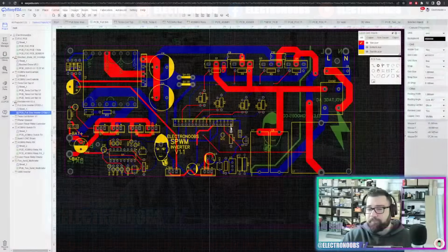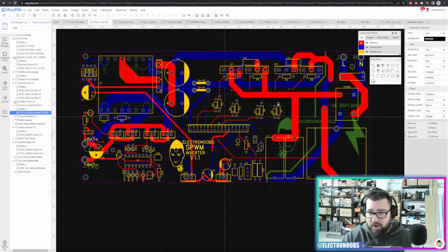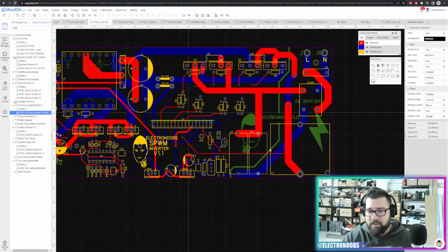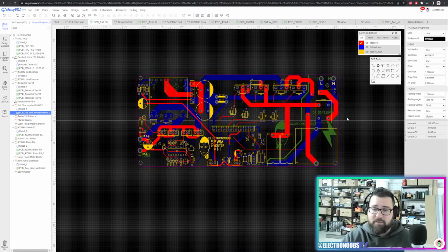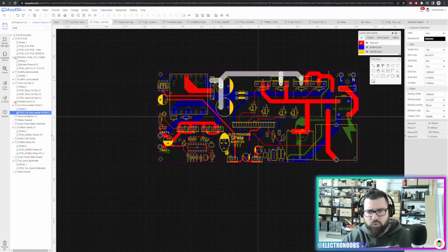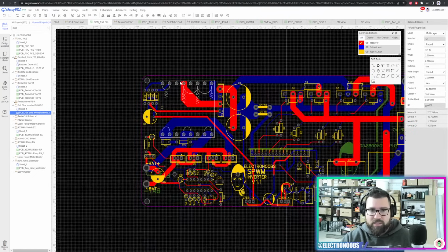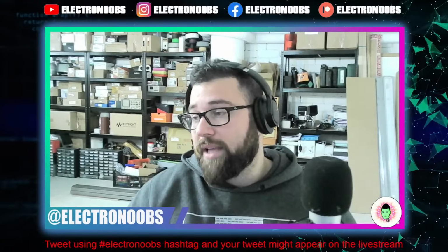As you can see, this one has the high voltage creation, then we have the driver, the IGBTs, the coil, and the filtering capacitor at the output, and this will be creating a full sine wave at the output without any kind of transformer, and up to 500 watts, and actually this could go up to 3000 watts if you add more of these transformers, because this transformer is the part that is limiting the power. So stay tuned for that.